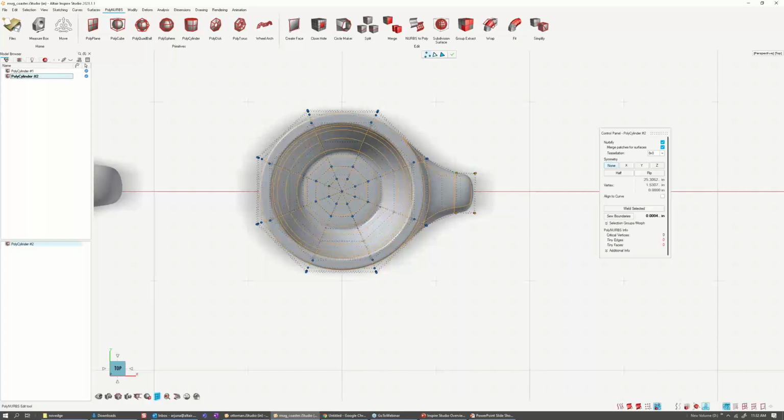And now it's time to just make some quick or finer adjustments to your model. So here we are in vertices mode, so you can select all 4 of these. And when you move your mouse close to the vertex, you will see these arrows. They let you drag vertices in a certain direction. So I can do this.